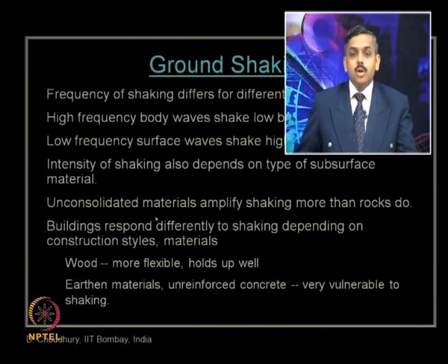Then, unconsolidated materials amplify shaking more than rocks do. What does that mean? Unconsolidated means the material has not consolidated or settled completely. For example, very soft clay material in an unconsolidated state will amplify the ground shaking much more than rocks do.